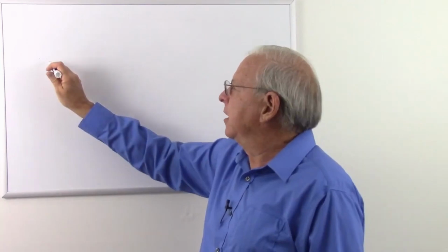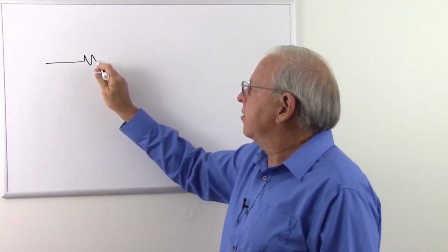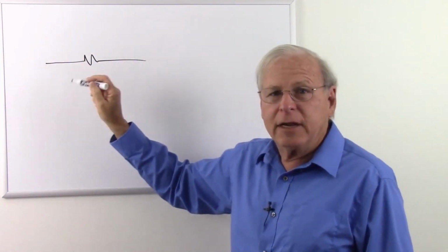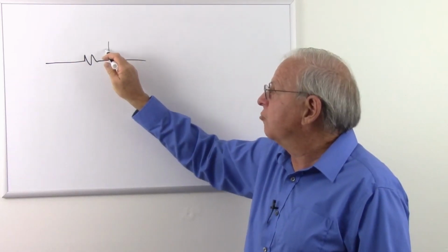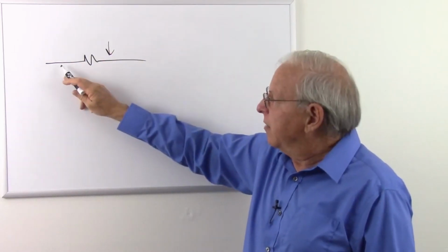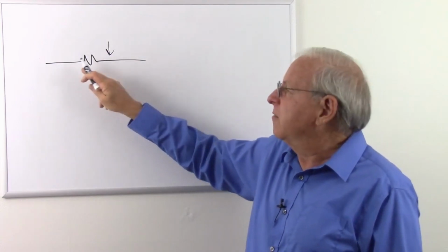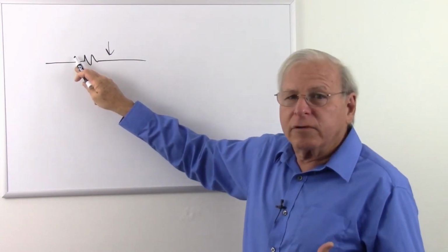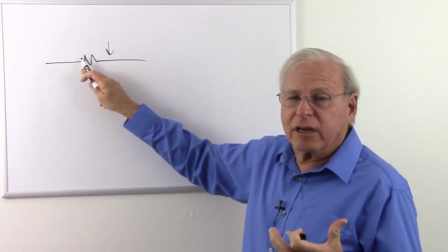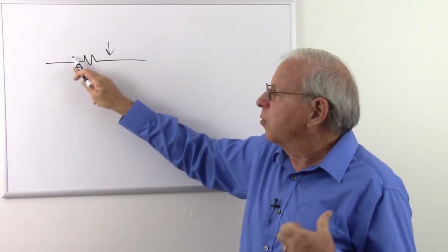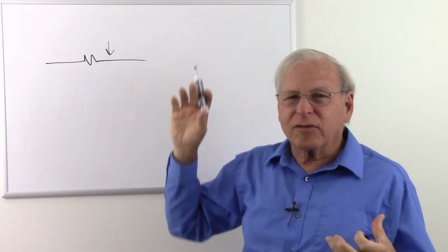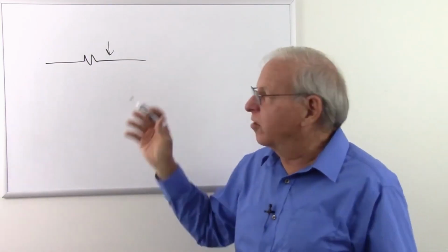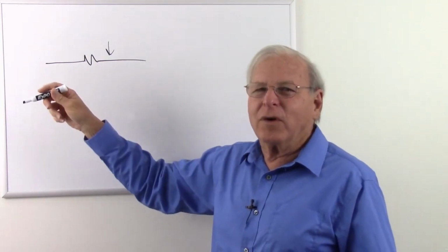We have our power coming into the house, and there's a certain amount of resistance in that line coming in, so only so much current can come in before we have a dramatic voltage drop on this side. Remember, when we have current flowing through a resistor, we have a higher voltage where the current enters the resistor, once again conventional current, more positive voltage where the current enters, lower voltage where it exits. Now this is alternating current, but the principle works the same whether the current is going one way or the other.